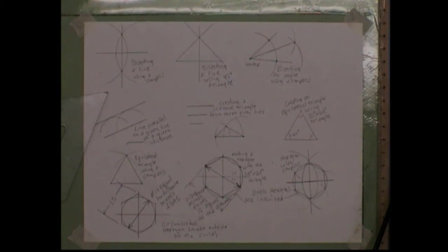So it's not where the circle is, it's where the polygon is. This is inscribed, so the distance across the points is the diameter. This is circumscribed, distance across the flats is the diameter. Okay? You guys good with that?